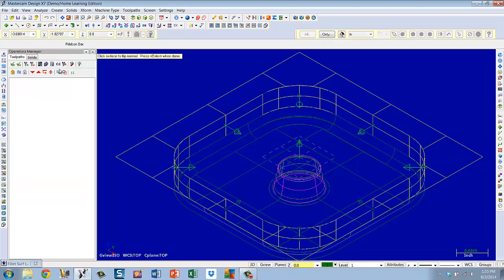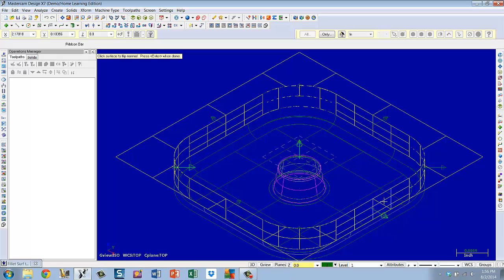We're going to try working here. Flip to normal. Gives you some arrows. It tells you which direction it's trying to create the radius fillet. My experience having practiced this part is that although it doesn't make sense, kind of seems counterintuitive, all of these arrows need to be pointing outward. You can click on the base of the arrow or even just the surface itself, as long as it lights up when you hover on it. Reverse these arrows.